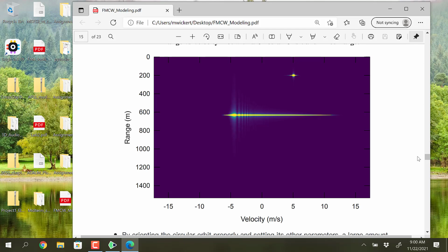you'll go up. If you change lanes, like I want to go around these cars, as soon as you change lanes, it gets a clear view. The heads-up display says nothing in front of you, and it brings your speed back up again. My wife has a newer car, a Honda Accord, and it works really nicely. It beeps at you when you're engaging somebody going slower than your set point, so you're supposed to change lanes if you can do it clearly, and then it beeps again to say it's lost lock, and your speed stays about the same.